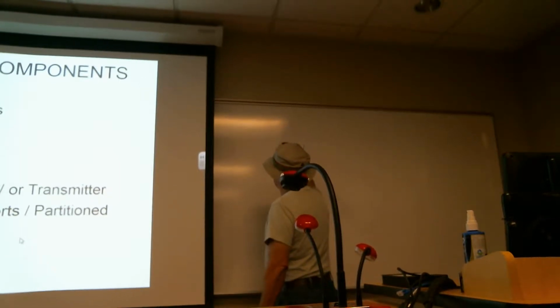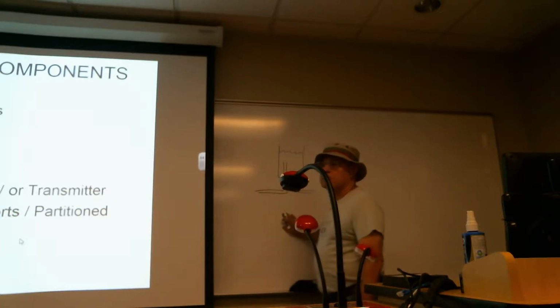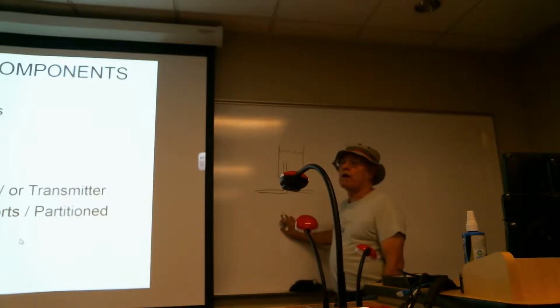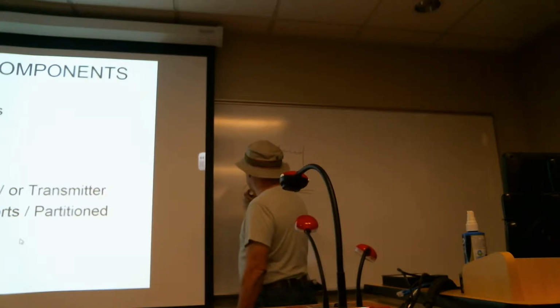If I drew a picture kind of like this, and I put a tube over here, and I have maybe just another outlet that's over here, the big tube would be referred to as a standpipe. It's just a device inside of the reservoir. The standpipe is always connected to the primary hydraulic pump, whatever it might be, engine-driven, electric, whatever. But we'll call this our primary pump.